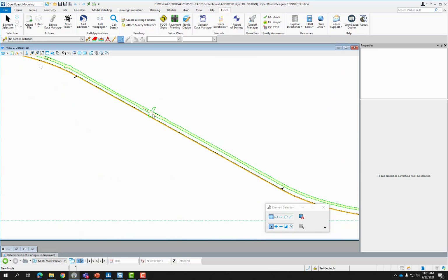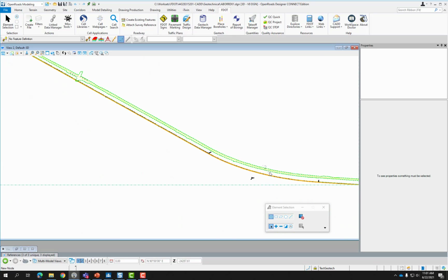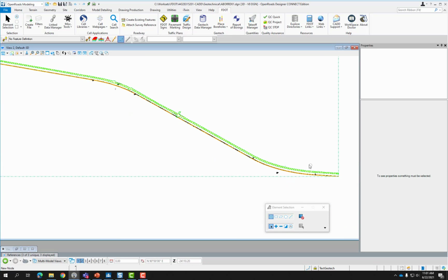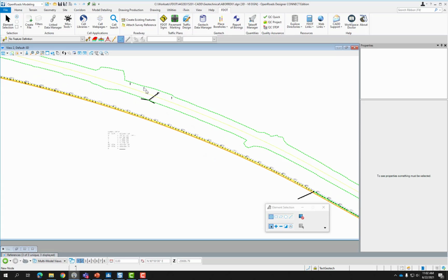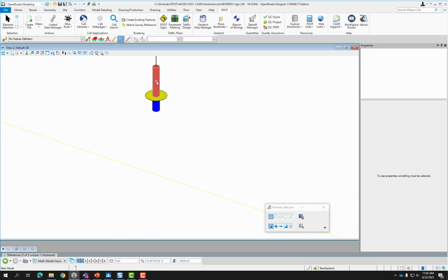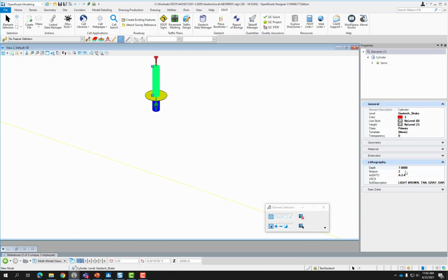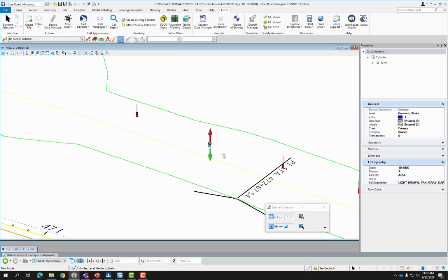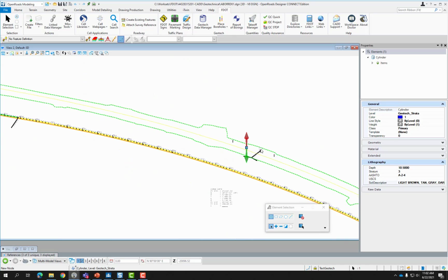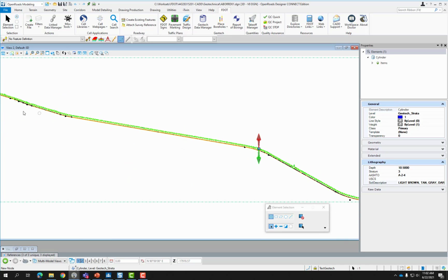Most of these didn't have any groundwater encountered, so they didn't plot. If you click on this strata, you'll see that that's the strata type 2, the soil type, and the soil description that came from the input file. If I look at the blue layer, that's strata 3, and the material type light brown. So that's really it for plotting these.